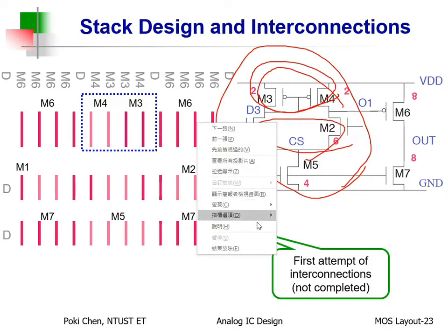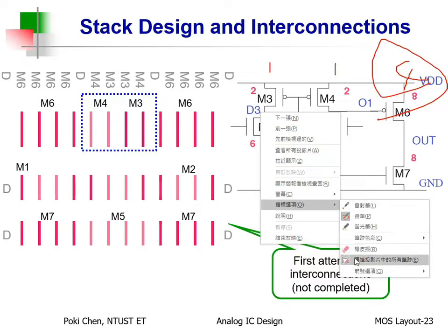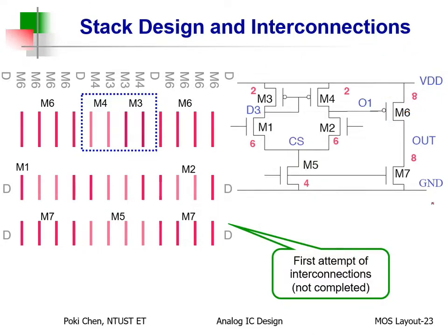Okay, right now we have 2, 2, 8. For common centroid layout, what is my first recommendation? Divide it by 2, right? So you get 1, 1, 4. And then the largest first, right? Do it. Just do it by yourself. So allow me to show you this. The original one, just like what happened here. Okay? Oh, it is not recommended by me.